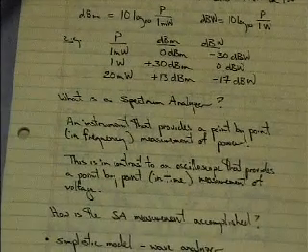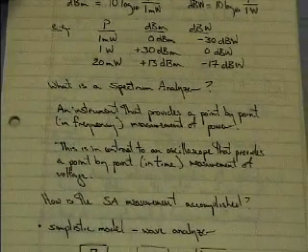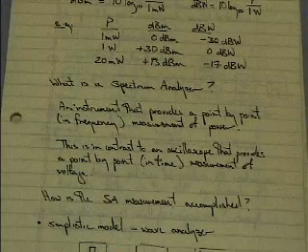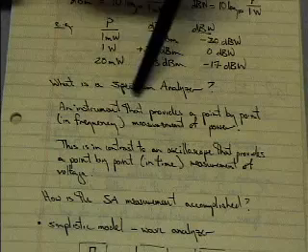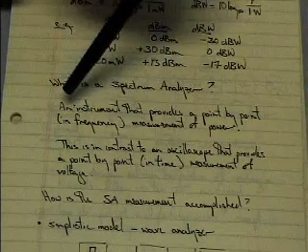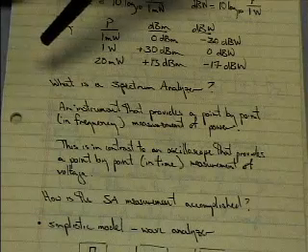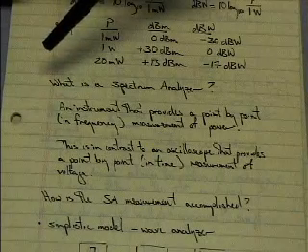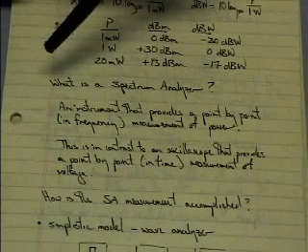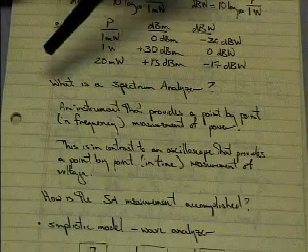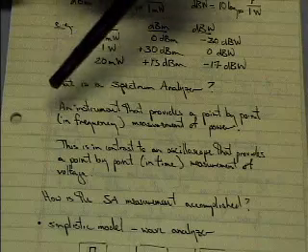Okay, so let's start off our discussion of spectrum analyzers by first stating, what is a spectrum analyzer? It's an instrument that provides a point-by-point, in terms of frequency, measurement of power. That is, as I look along the display on a spectrum analyzer, the x-axis is going to be frequency and the y-axis is going to be power. So I can look at how much power is at any particular frequency using a spectrum analyzer.